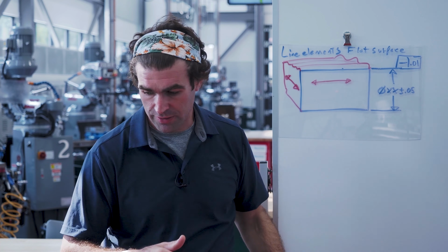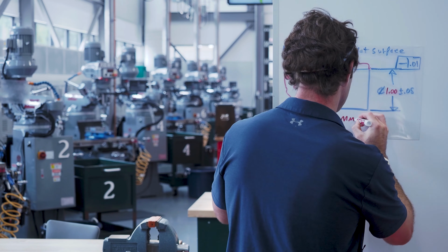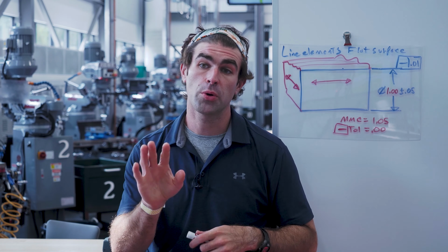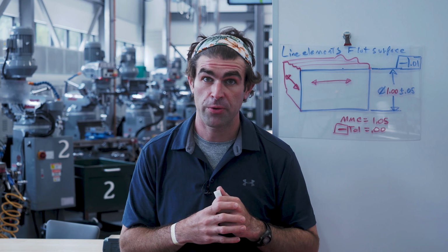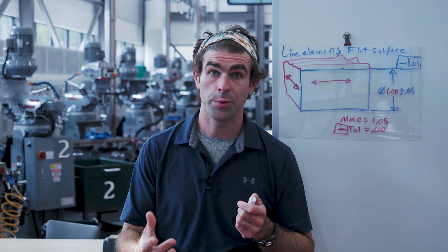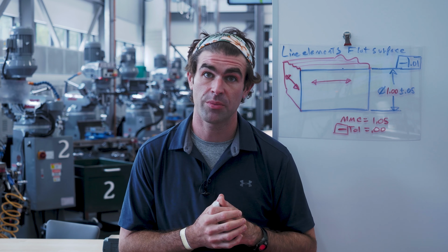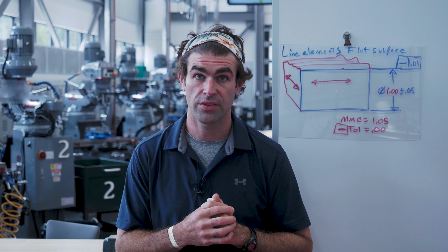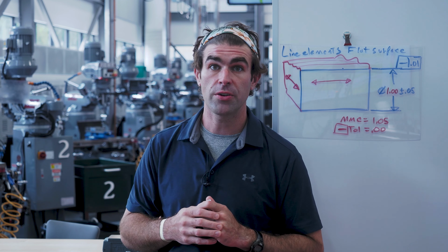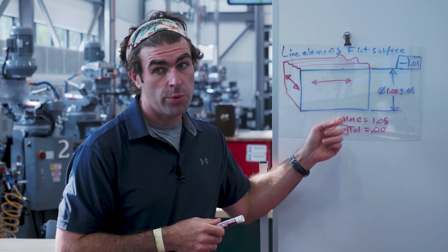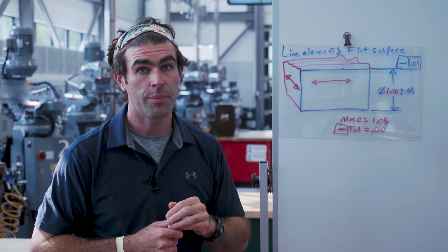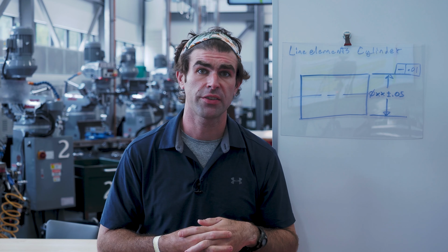You don't have, and let me put a real number here. As you approach that boundary of perfect form, you start to lose out on the straightness tolerance that you had. So if the block comes in at MMC, no straightness tolerance. If it comes in under MMC, you can start to use the straightness tolerance, but only up to 10 thou. So let's talk about our next case.